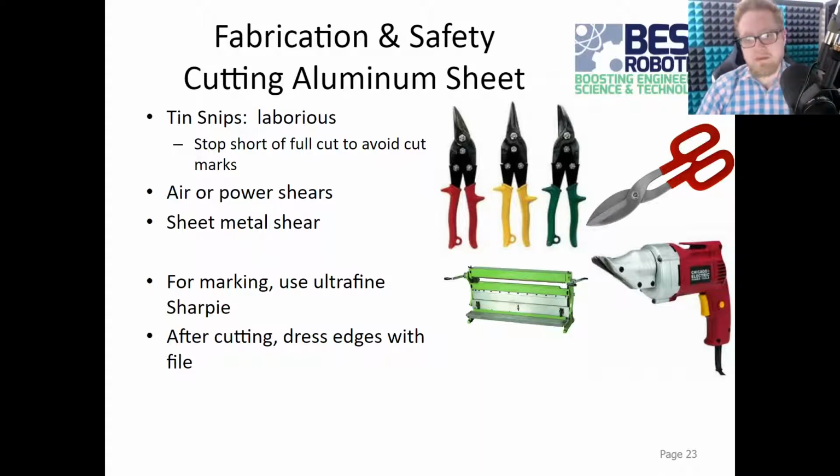The main way being tin snips or powered snips. That is the easiest way to cut through the sheet, but that will often give you a rough edge, and that can distort the edge of the material as well. So if you are using it for something that you need to be very flat, or you need the edge to be very nice, the best way to do that is using a hand tool like a hacksaw, or to use specific sheet metal machines like a press or a shear, and that will give you a really, really nice edge. However, if you don't really care if it's a little wavy or if you're intending to bend it later, tin snips will work just fine.